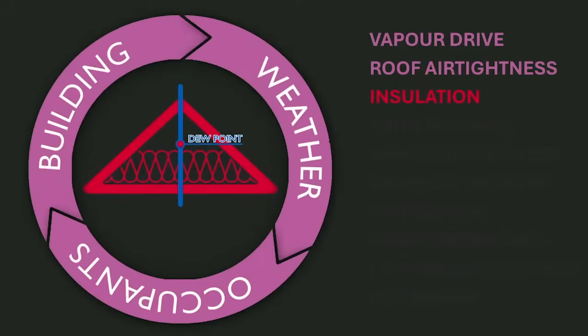Achieving a good understanding of the hygrothermal performance of the insulation is important, as part of the role of construction membranes in roofing is to help balance these characteristics, limiting the risk of harmful moisture issues. Without good information and solid specifications for the thermal envelope, ensuring vapour control layers and underlays with the correct performance characteristics are chosen for the project can be difficult.